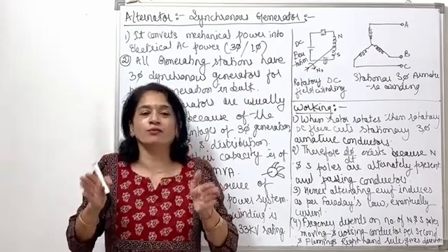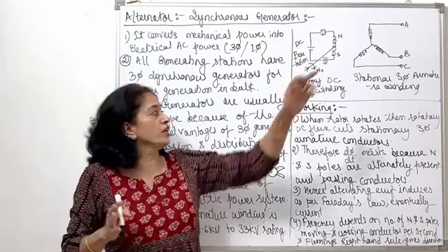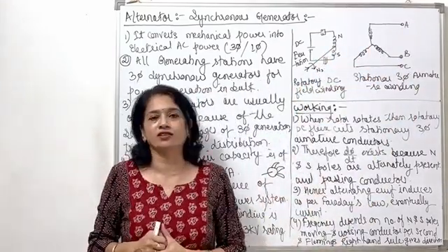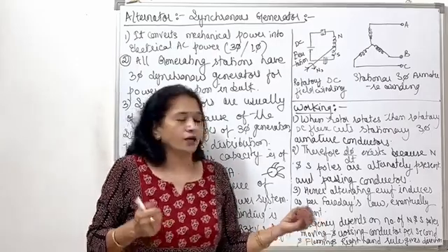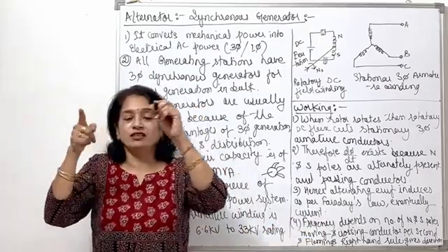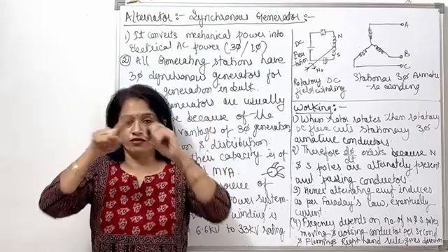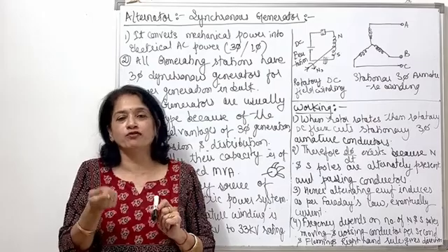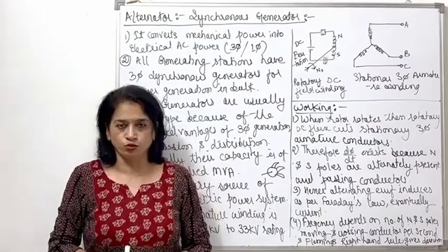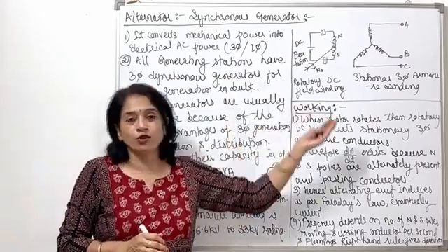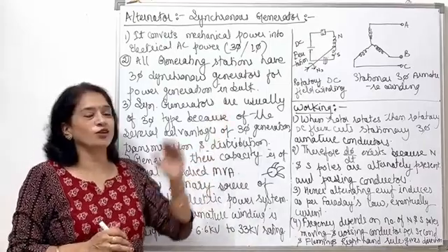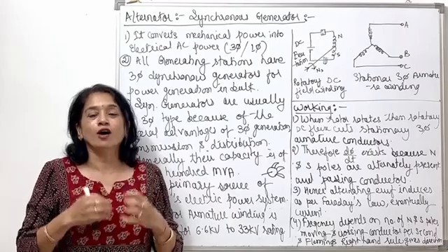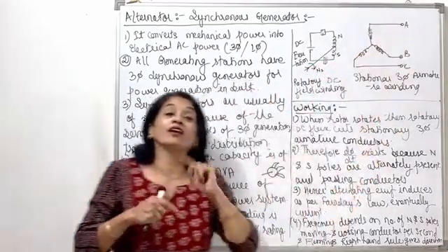But here, I am giving you a brief of how the 3-phase AC EMF is being produced, which I explained right now. The polarity of the EMF in these conductors placed in the slots of the stator is found with the help of Fleming's right hand rule. The things I explained related to the synchronous generator give the perception of how it works, how EMF is induced across it, and why it is AC.